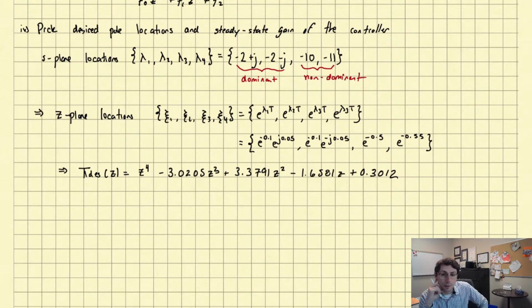Okay, I remind you though, again, in discrete time, it's not necessary that all the coefficients of this polynomial have the same sign, right? In continuous time, we'd say, hey, wait a second, this polynomial is not Hurwitz, not stable. But remember, in discrete time, it's different tests. We're not using the same tests as continuous time. So this certainly is a stable, or Schur, polynomial. It has these roots.